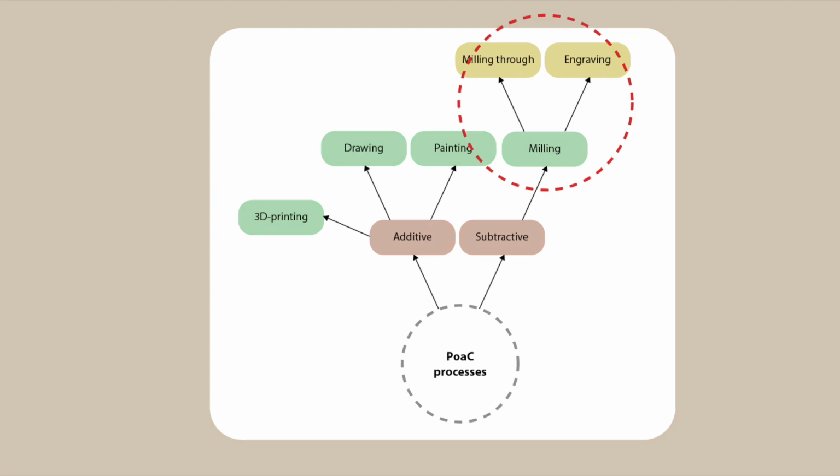The reason for this decision is that milling requires little pre-processing, creates a permanent effect which is both perceivable visually and physically, and is a process with many different changeable parameters, such as milling depth and milling bit type. Furthermore, the milling paths allow placing additives such as 3D printed paths or paint onto milled areas as a post-process.